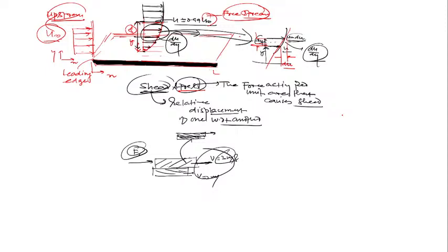And shear stress is proportional to the gradient, and the proportionality constant is what? Viscosity, that you know very well. In fluid mechanics I will discuss it. So as I also told you, you have seen the upper layer and lower layer, and that causes the gradient, and this gradient causes stress to develop. Due to this gradient in the fluid layer, there is a development of shear stress, and that shear stress is proportional to the gradient du upon dy, that is, tau is proportional to mu into du upon dy. Clear? Mu is called viscosity, and this is called Newton's law of viscosity. Clear?